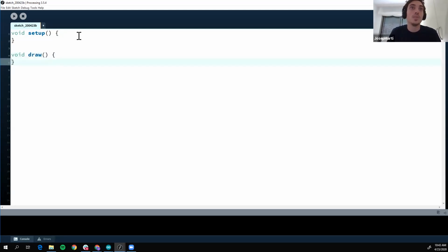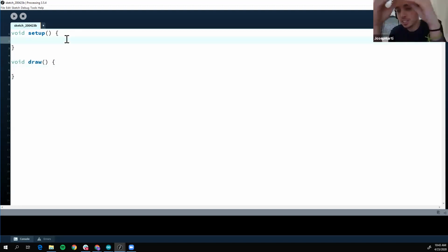So as in Arduino, the void setup is just setting up the major parameters. This only runs once when you start the program. Then it will not run again. So if you want to make some calculations, for example, that you only want to run once, you can make them here, so you avoid the program making them each loop.